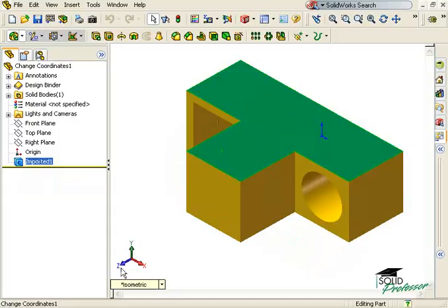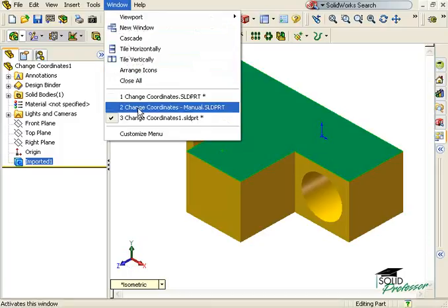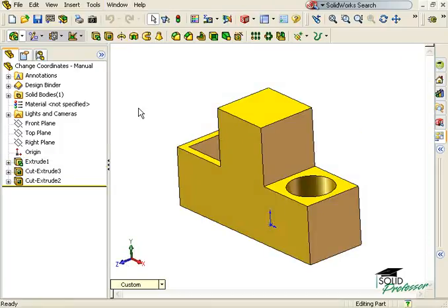If these two techniques don't address your reason for reorienting your part, and you truly wish to change the global coordinate system within SOLIDWORKS, you'll have to go through a somewhat tedious manual process, as SOLIDWORKS doesn't allow you to change the global coordinate system directly. Instead, you have to change the part itself, including its sketch planes and directions from the ground up. The sample part I have here is quite simple and can be reoriented easily.